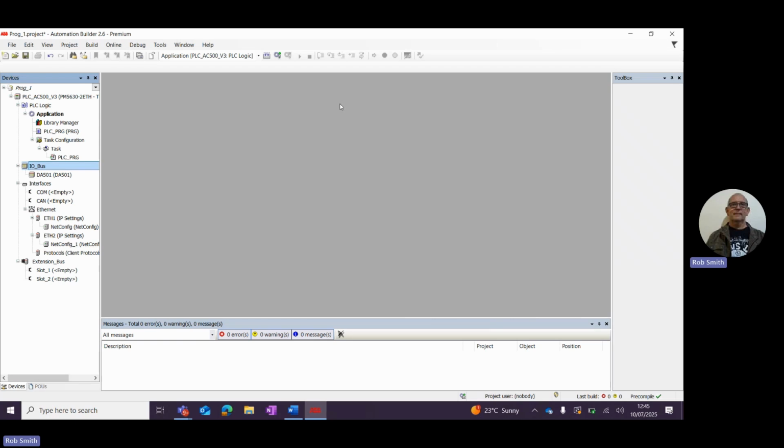And we can see now it's appeared in the I/O bus. So now we've got the PLC connected and the input output module connected, all into this program that we're creating. Remember I said that there's only 3 items physically connected to our PLC. So we've got a red lamp, an orange lamp, and a green lamp physically connected. There are no other connections, so there's no inputs, no other outputs like motors or conveyor belts and things like that.